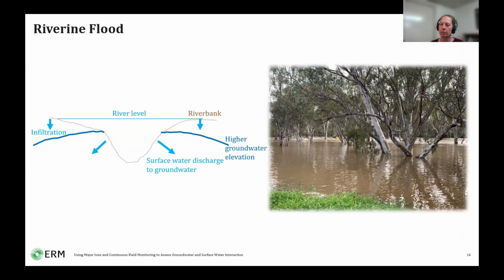At peak flood flow, the river was flowing really fast. I actually saw a couch float past at one point. And then the river stayed outside its banks for multiple weeks. While under flood conditions, the groundwater table, again, I haven't measured this, but the groundwater table would most likely have been lower than the river and therefore able to receive outflow of surface water, with the river acting as a losing stream. You can see that in the cartoon.